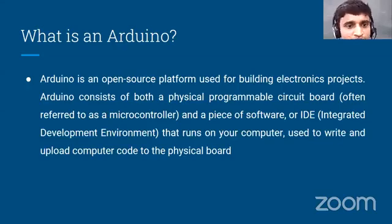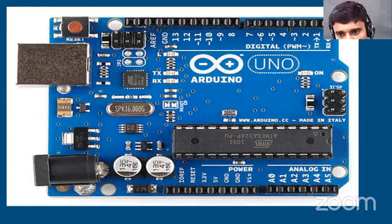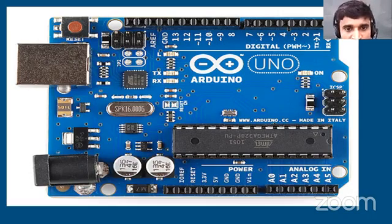you require an IDE, software to put your code into the Arduino. You write the code in the Arduino IDE, then upload it to the board. So this is the board diagram, a simple Arduino Uno. There are digital pins 1 to 13, analog pins A0 to A5, and a power supply section with 3.3V, 5V and ground, a reset button, and jumper settings.